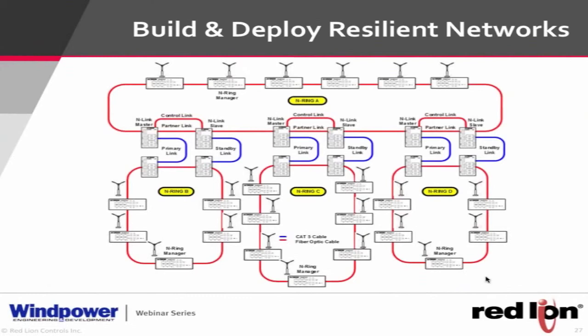And so we have redundant inputs on the power supply on all of our Ethernet switches, so you could have multiple power supplies, or you can have a power supply and a battery backup, however you felt most comfortable doing it. But if you were to have a power outage right here, say the switch at the very top, if you were to have that switch fail for a power outage or whatever it may be, the rest of the network is still up and going.